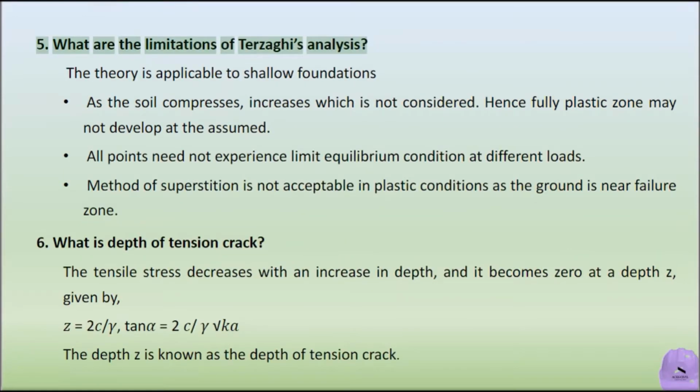5. What are the limitations of Terzaghi's analysis? The theory is applicable to shallow foundations. As the soil compresses, the strength increases, which is not considered. Hence a fully plastic zone may not develop at the assumed depth. All points need not experience limit equilibrium condition at different loads. Method of superposition is not acceptable in plastic conditions as the ground is near failure zone.